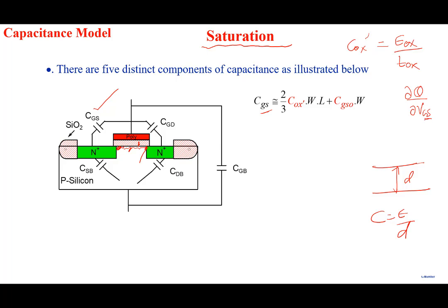for example, let's say you look at the linear region. You know that transistor characteristics IDS versus VDS for a typical VGS will look like this, right? Suppose you're here, very close to the origin, in the linear region. You apply a VDS of, let's say, 10 millivolt.